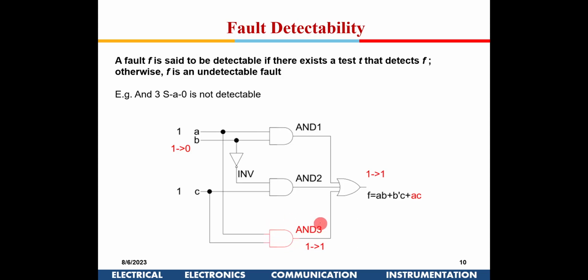So once you have a redundant gate which a designer has put in for meeting timing requirements and reducing hazard, for the test engineer this becomes a nightmare, and he will not be able to detect this fault here. So all faults may not be detectable. That should be known, otherwise we will spend time and effort trying to identify these faults. You can also say it the other way around.